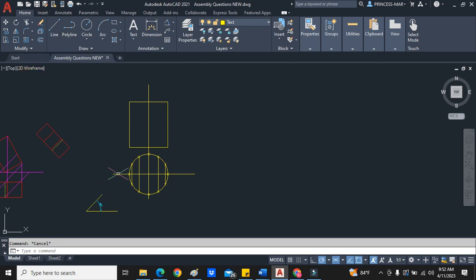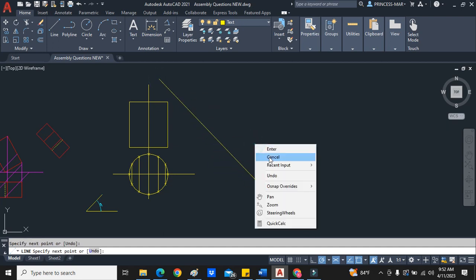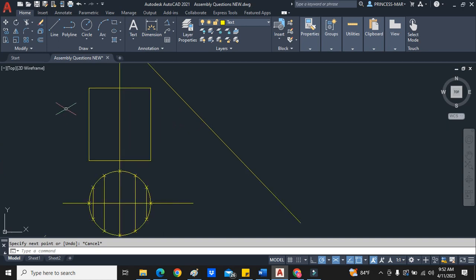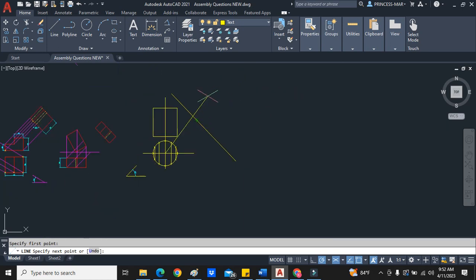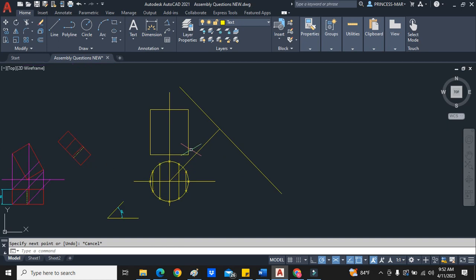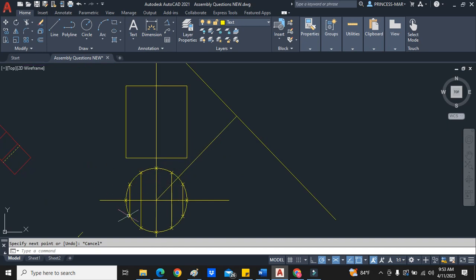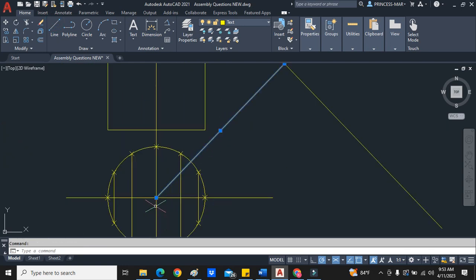Alright, so the first thing is I'm not going to project up the figure first. I'm actually going to project up this line, or the plane that I'm using. So 45 by 45 is simple, because it's just two 45-degree lines. You understand that? From here, we are going to project up our center. Now we're going to transfer this circle right here. You understand? To transfer the circle, we're going to use this line, but we're going to use the divisions that I created just now.